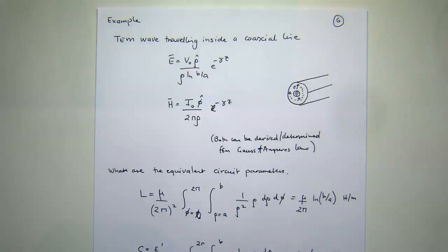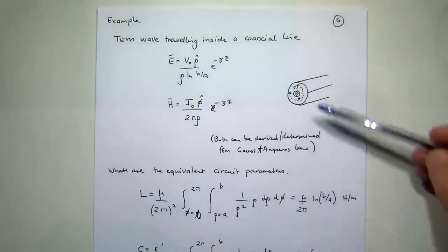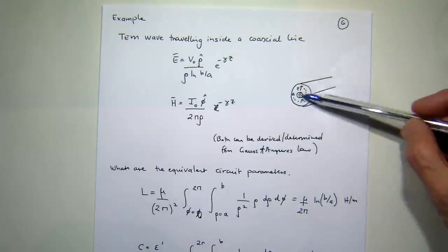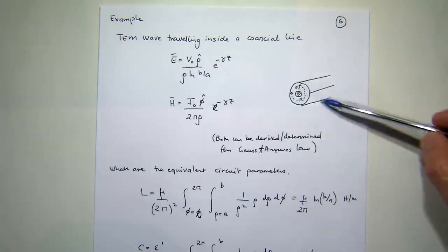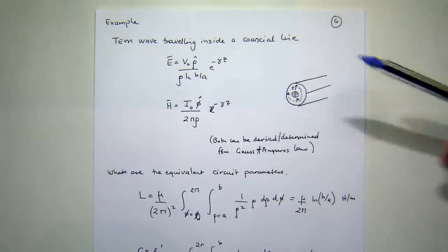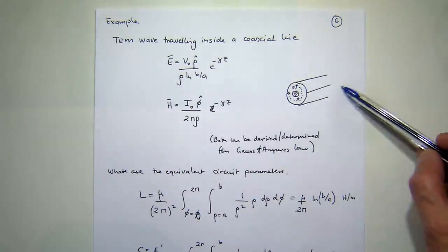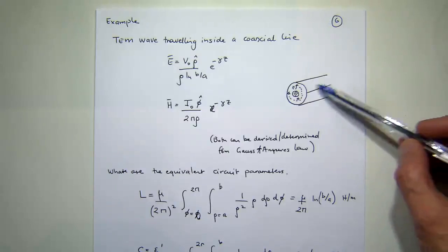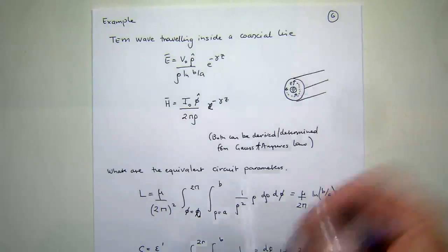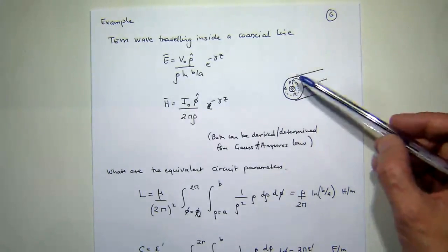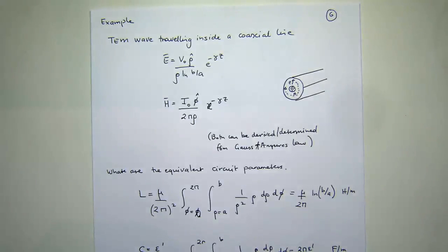All right, you've all used coaxial cables. Great. Essentially, a coaxial cable has a thin wire which acts as a core. Usually you've got some dielectric, and the core is used to transfer the signal of interest, and you've got an outer ground sheath. Usually they also put plastic around it just to protect it. Now the core in here could be air or it could be some other dielectric material.